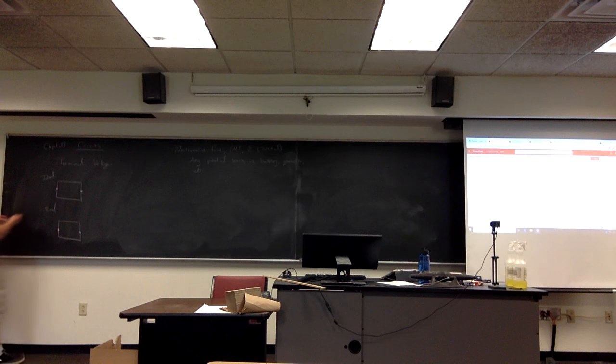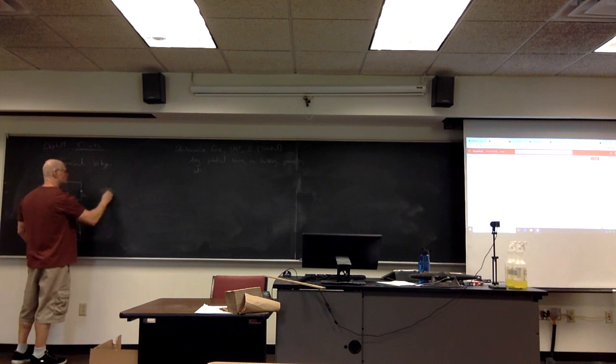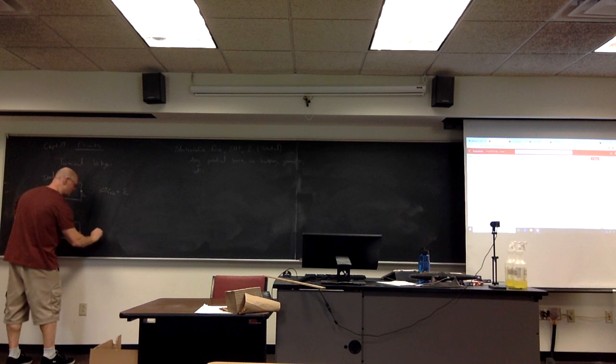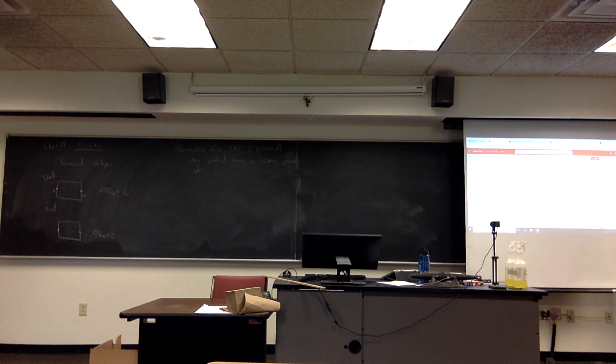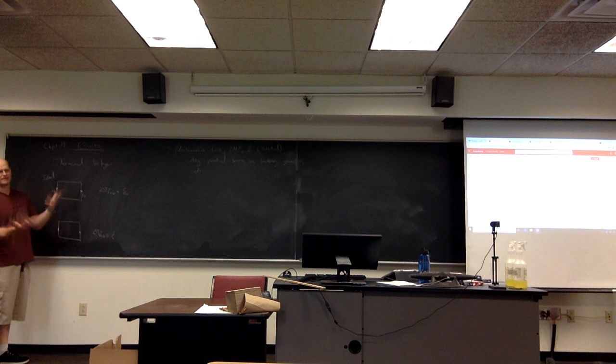A terminal voltage means, if I have two points that I'm measuring the potential across, say A and B, then with an ideal battery or a real battery, as long as I'm not running any current across it, the terminal voltage across these particular points is simply equal to that of the EMF. So whatever is supplying the actual potential. As long as I have no current running through either an ideal or a real battery, the potential difference across the terminals, or our terminal voltage here, is simply equal to that of the EMF. Okay, so whatever is actually supplying the potential.